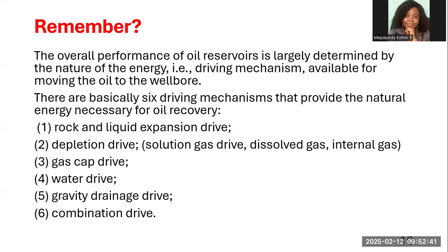You know your water drive, you can have the strong water drive, weak water drive, and the partial water drive. Your gas cap drive, there's the energy from the gas cap. Your solution gas drive is a depletion drive, because as gas evolves from the oil as a result of pressure drop below the bubble point, you have depletion of such drive.